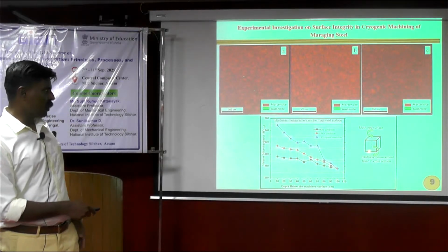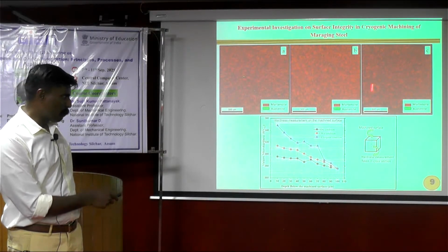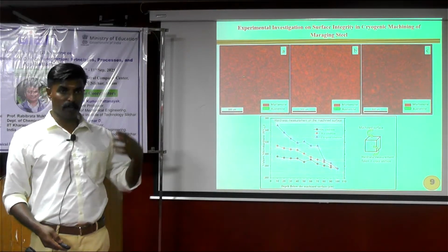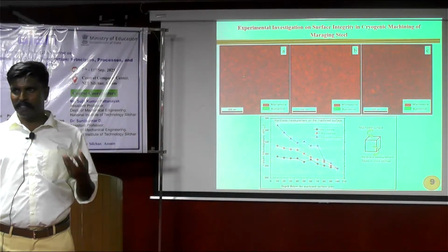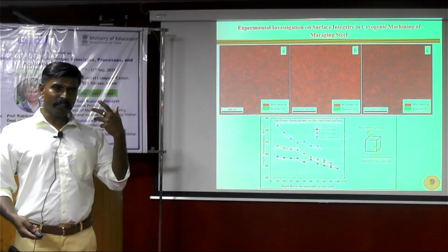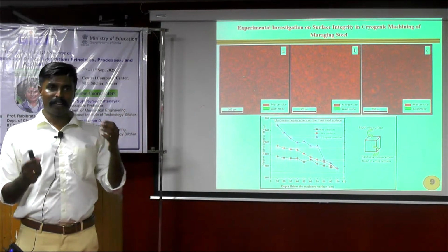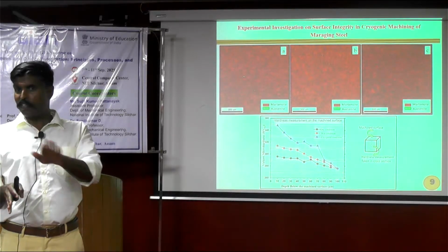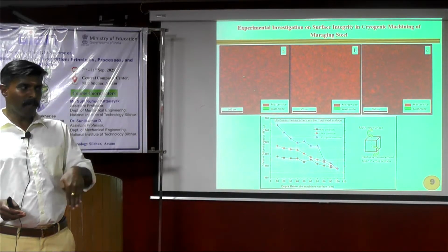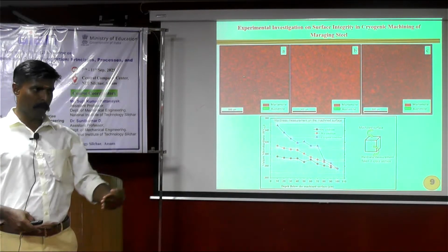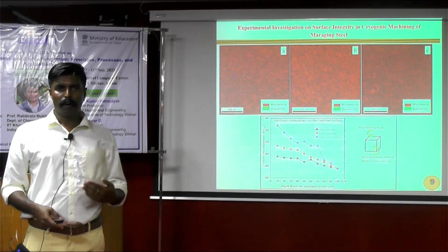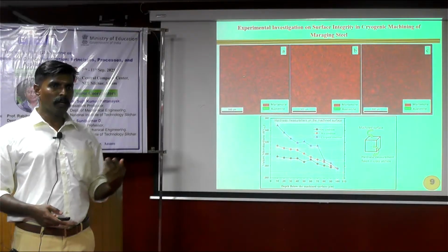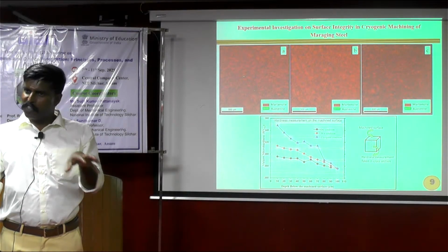Then this is a machined surface, and we have taken subsurface hardness. We are very keen to know the mechanical property. We have seen there is a significant difference in the grain morphology and in the grain boundary fraction, but there is no phase change. Then across the machined surfaces, we have taken hardness measurements to see what the variation in hardness is due to the changing cutting fluid environment.